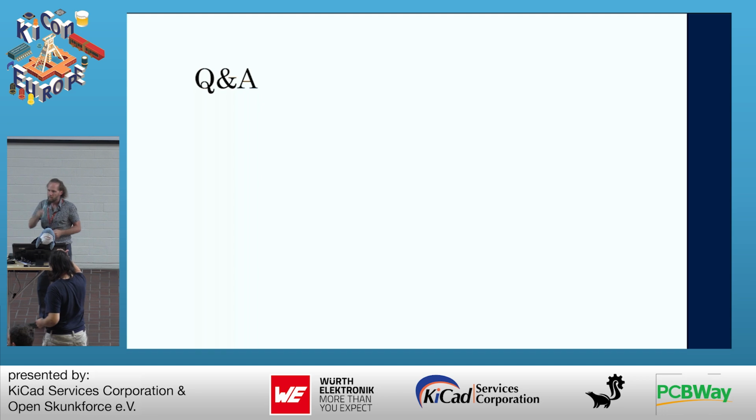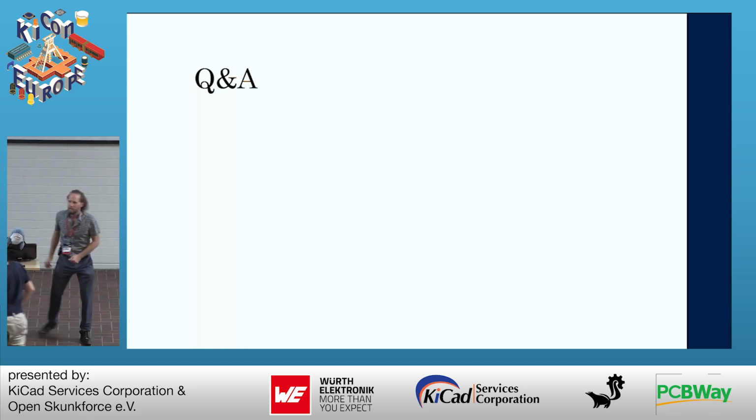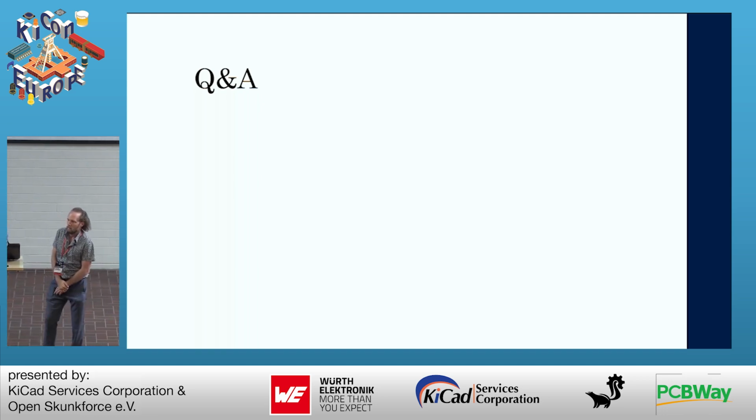Your example is very clear, because with clearance you can see it as you go along. If I have a length constraint, how does it work, when it's only when you're running a check at the end? Your router's not going to save you on length constraint.